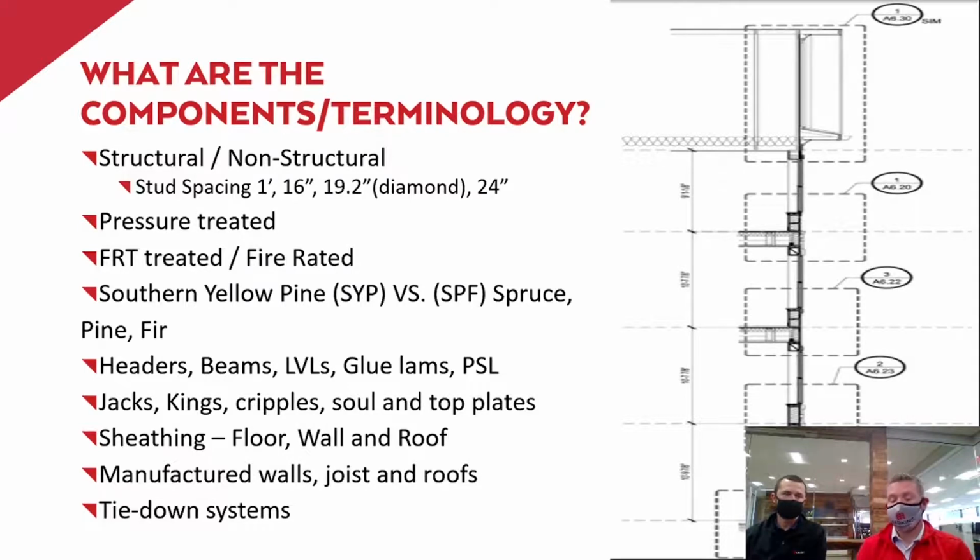That being said, you also have to check your wall schedules because the second plate may not always be a 2x. If you're building a 2x4 wall, the second of the two top plates may be a 2x8 to span a demising wall for fire blocking. This is something that gets missed all the time, and you have to make sure of it when you're doing your initial inspections. You check your wall schedule, and wall 5F may be a 2x4 top plate with a second top plate that is 2x10 that covers the adjacent wall as well and makes up your fire blocking for that wall system. That's a great point there.